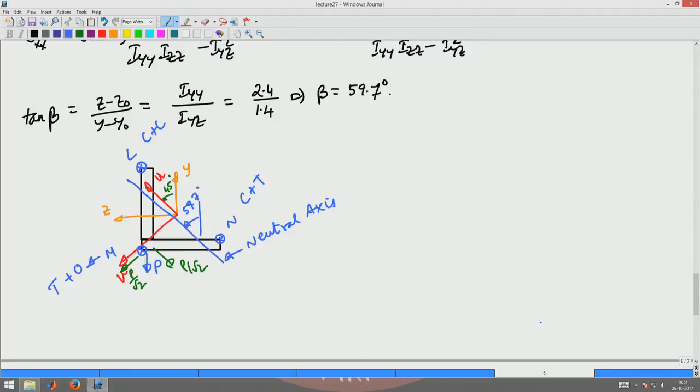So basically now you will find that M would be in tension, L would be in compression, and N can be in tension or compression depending upon which is dominating, because it is a combination of a tensile stress and a compressive stress. Okay, that depends on what the orientation of the neutral axis is. So this kind of analysis you should be able to do to quickly tell whether a given point will be in tension or compression due to bending stresses.